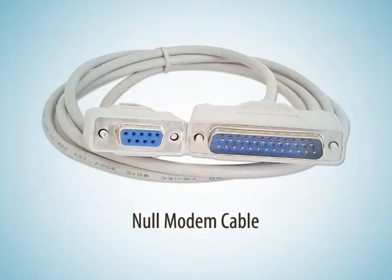There are several standard cables defined for connecting a PC to a device such as a modem or a printer or a mouse. Now that the modems are defunct, the same cables are used to connect PC to PC or PC to other devices. These cables are popularly called null modem cables, since no modem is envisaged at the other end, but the software in PC works as if it is still sending data to a modem. Many types of such cables are in use, and we will discuss only 3 main types here.